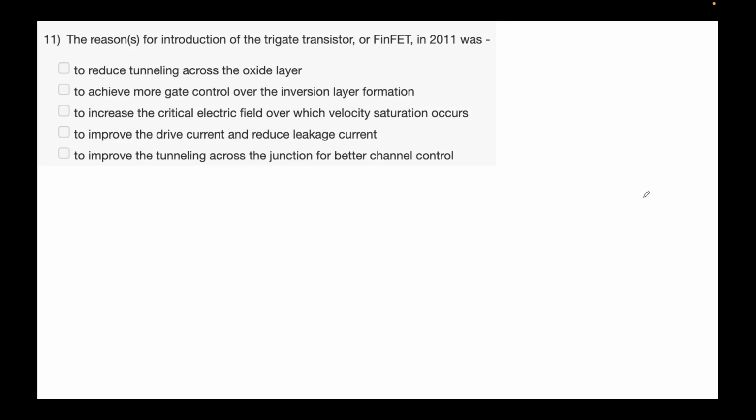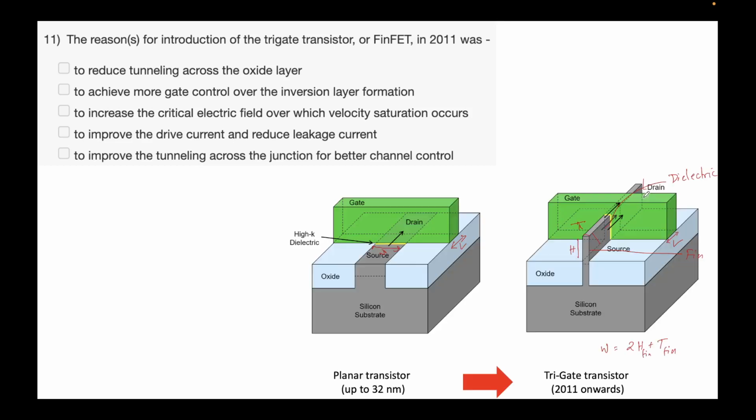The second thing was there are a few other problems that we encountered. So this asks why FINFETs were introduced. These are from lecture slides again. On the left you have a typical planar transistor. By planar we mean you have a source over here, and a drain behind this green barrier of gate. Yellow is your dielectric. You can again see the high K dielectric. We're talking about 2011, and high K dielectric was 2007.